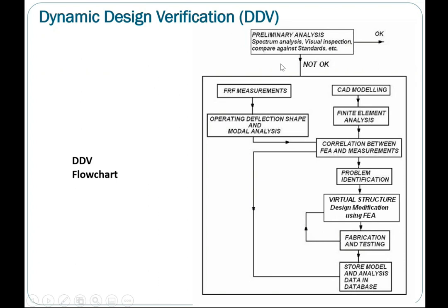So preliminary analysis is like your CBMs. So the 4 points, which are at the driver and driven, NDE and DE. So you go through all the new machines, just commissioned, not yet in operations. So by right, everything is new, right? Everything should be well balanced, right? No wear and tear, and it should give very good vibration levels, right? Because everything is new.